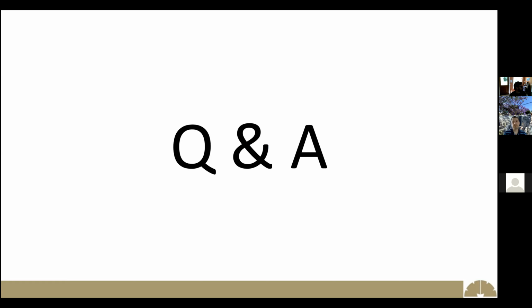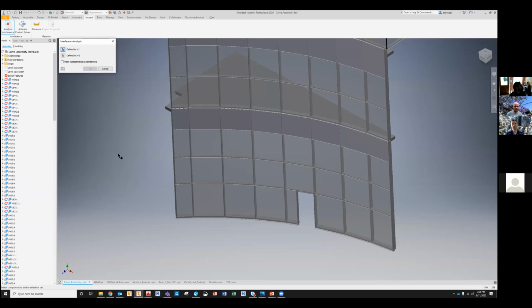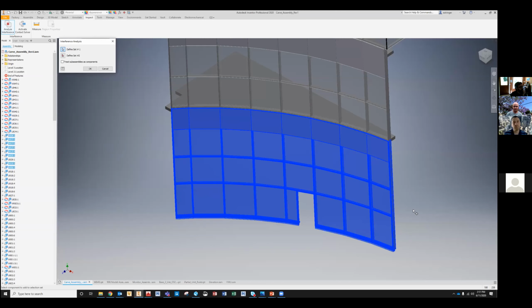There is. In Inventor, there's a built-in thing called interference detection, or Analyze Interference. For any assemblies or anything that you have open, you can select different parts, and it will do that for you automatically and highlight the areas. I think it'll tell you what area is interfering.